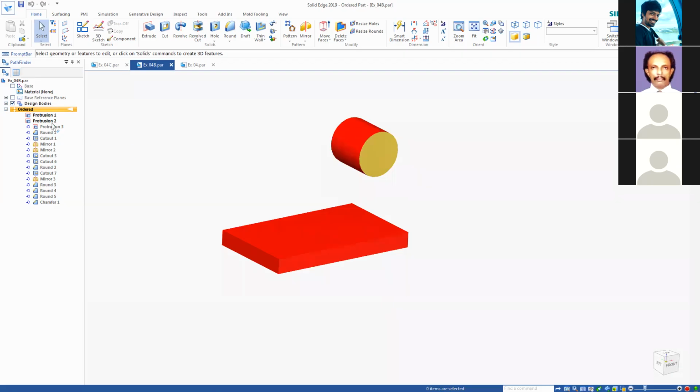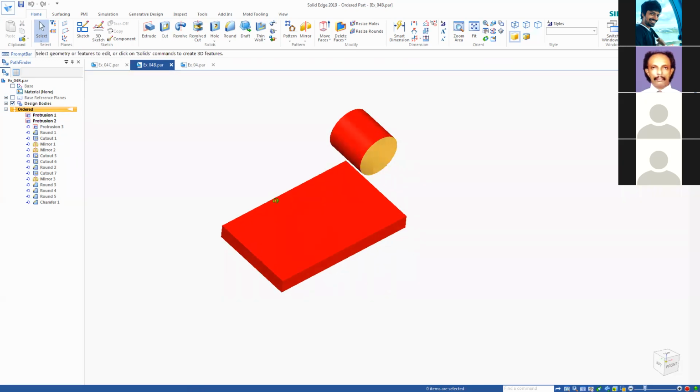So this is the first one. Maybe most of you obviously start with this one. But you see the difference. I don't have here the fillets, the holes, nothing, just a very simple thing. So that is what you say, a simple sketch. But it should not always be like that. You decide whether to include your fillets, the corner fillets or the radius with the base feature, maybe or not. That is depending on your